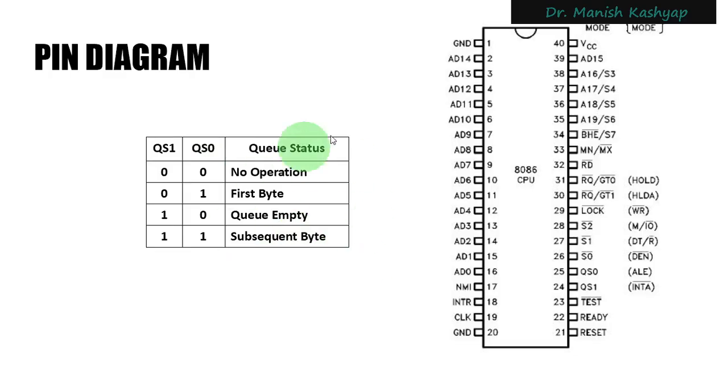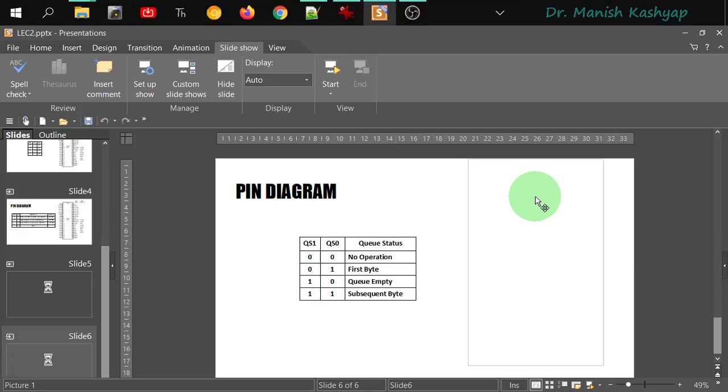So this is what we mean by these pins, and they can be used in the maximum mode of operation. In the current lecture we will see the operation of maximum mode, and we will find it highly similar to minimum mode, with some differences in the hardware implementation, right? These status signals that you see here, S0, S1, and S2, will be applied to one IC, and that IC will be generating the control signals for the external world. I mean, how this 8086 microprocessor will deal with the external world. Those are all the things that we are going to see in the current lecture.